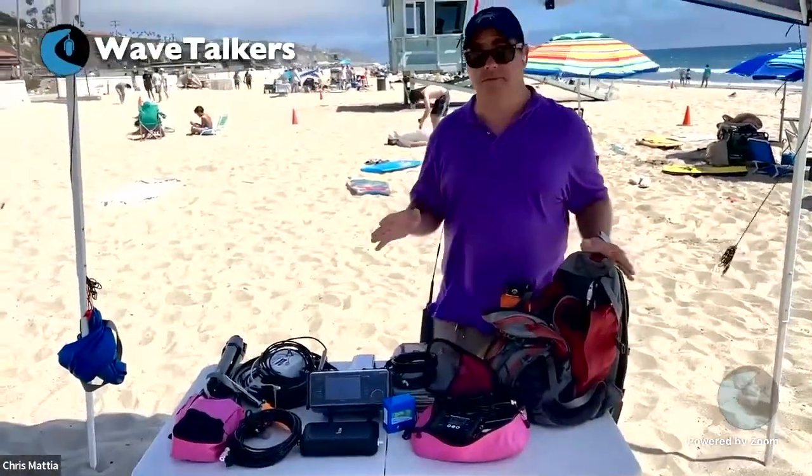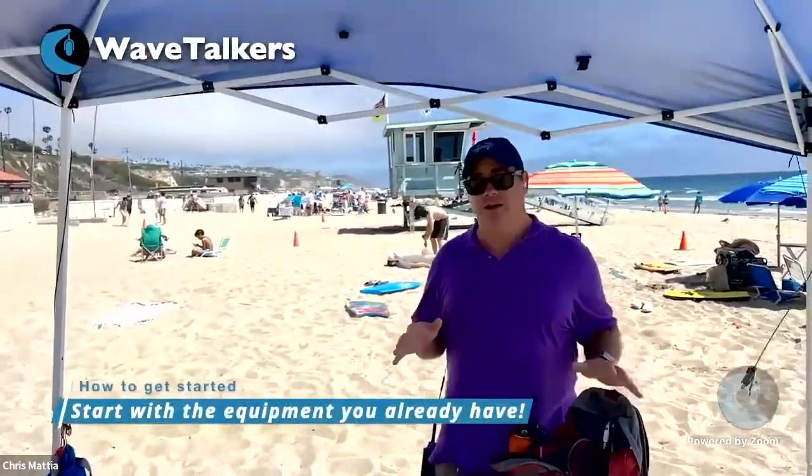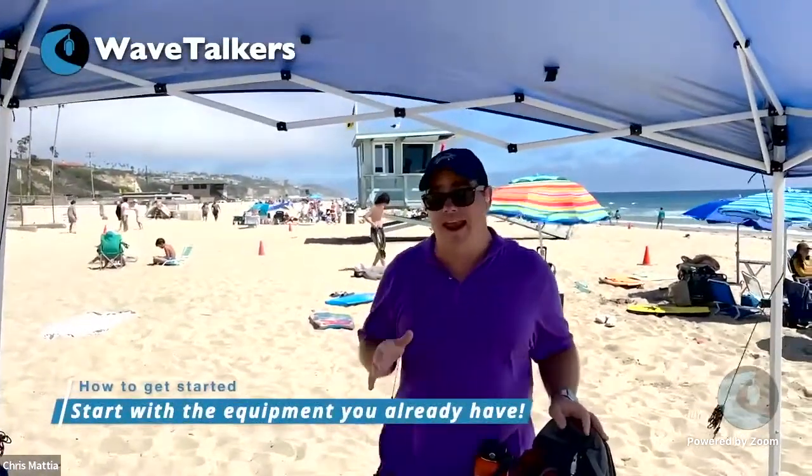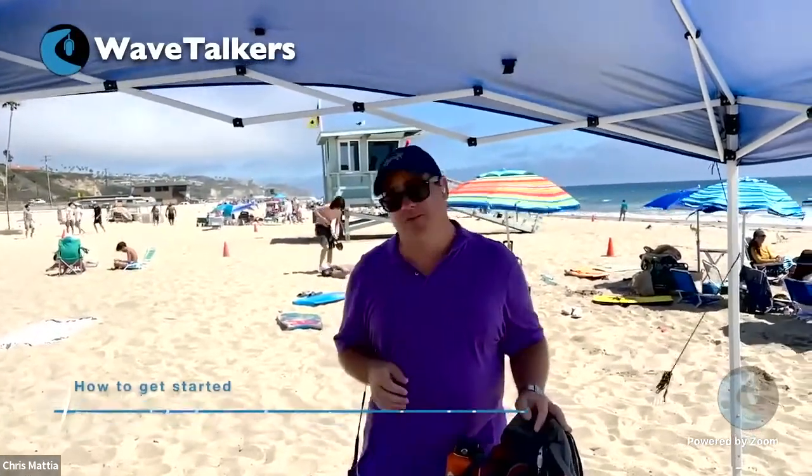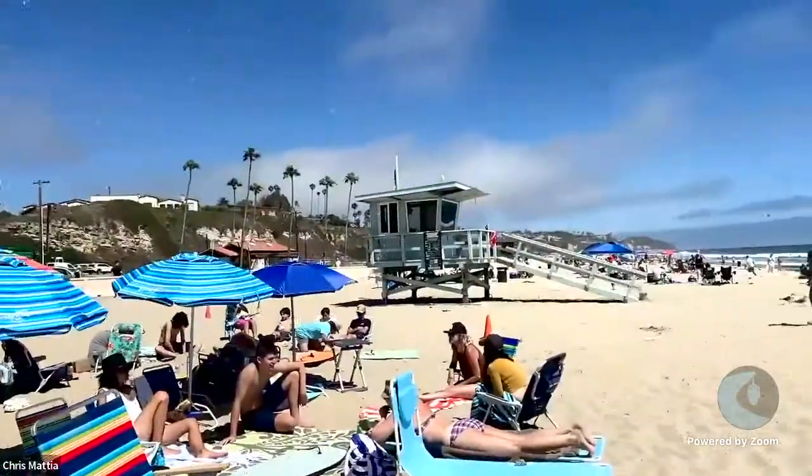Your equipment is going to be different, but what you really want to do is just start off with whatever you have. As my friend W0DHG likes to say, use the crap from your garage if you need to. Just make sure that you've got a full operating system before you head out to the field. You need to make sure you've got power, your transceiver, your antenna system, and your computer, and everything's ready to go. So we're going to go ahead and get all this stuff set up, and then we'll try and send some Winlink traffic via both VHF and HF.